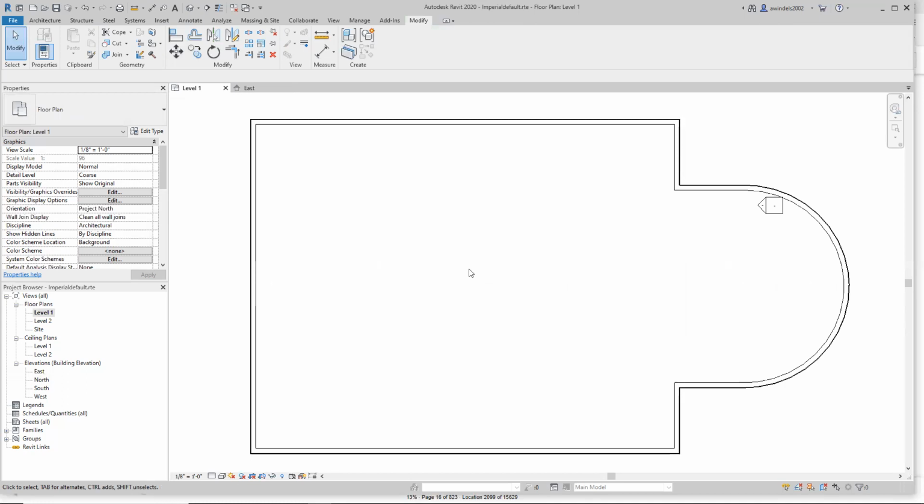Anyway, moving on to some of what's in the view control bar, we're going to go to the scale. So scale is important with mostly annotations, dimensions, and stuff. So here it is. Let's change it from 1/8 of an inch equals 1 foot. Revit's commonly in architectural inches. Okay, not tenths and hundredths of an inch like civil engineering and surveying usually is. It's more for structural construction and architecture.